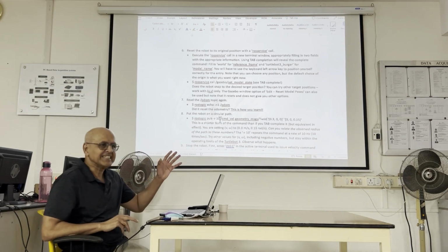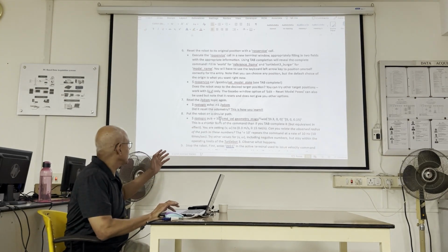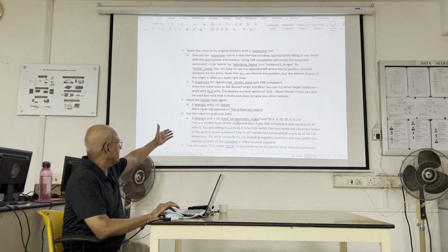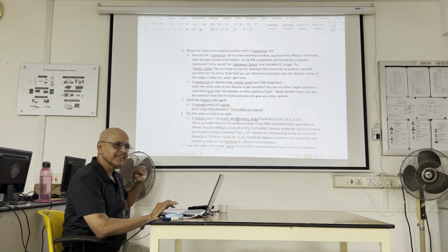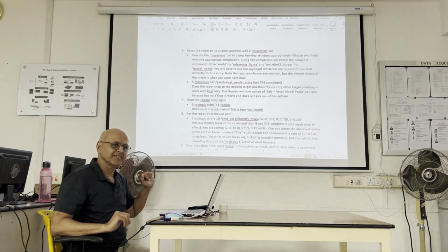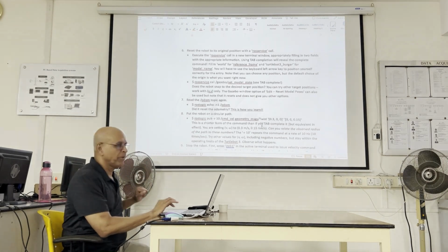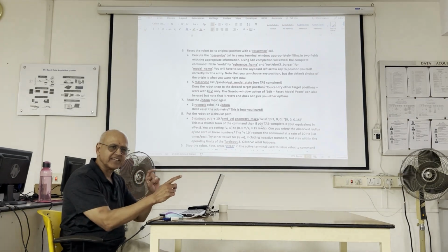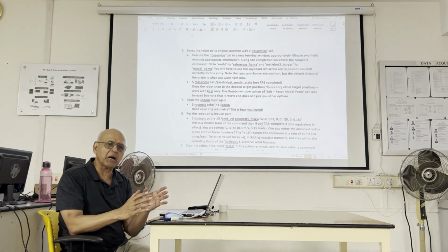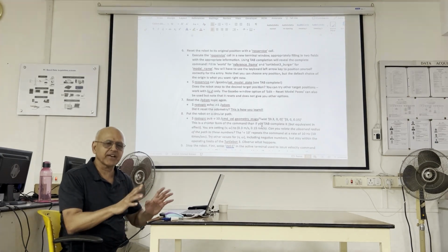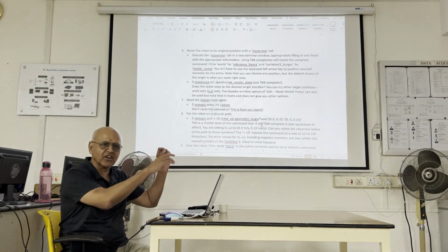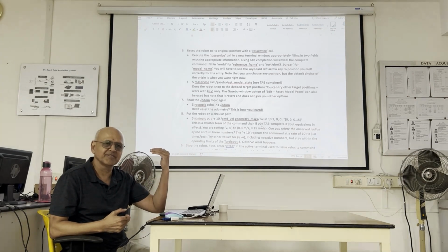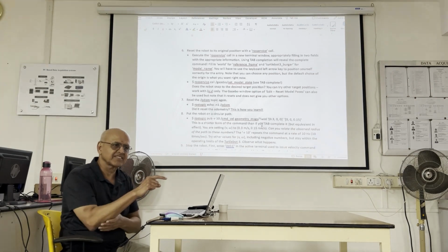Here, all you're doing is stopping the command, right? So suppose I publish this, you know what's going to happen? It will run forever. Even if I stop publishing, you know what I mean by stop publishing, right? I hit a Control C, and that means you're not publishing to the topic anymore. There's no connection between the bulletin board and the robot. The robot has already grabbed it, and if you're not giving it new values, it's going to run with the last value. So that's a bug.